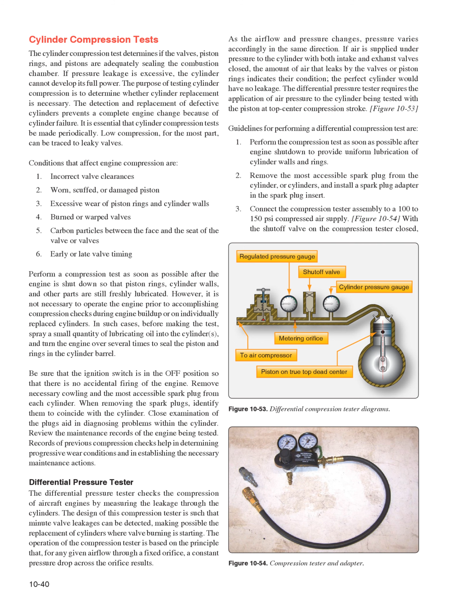Be sure that the ignition switch is in the off position so that there is no accidental firing of the engine. Remove necessary cowling and the most accessible spark plug from each cylinder.